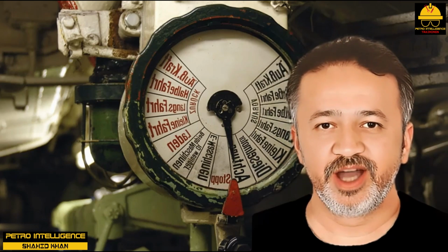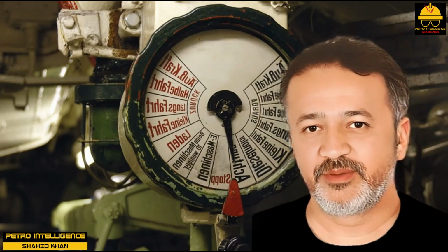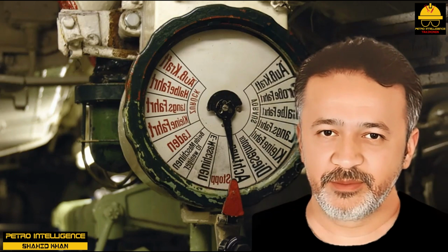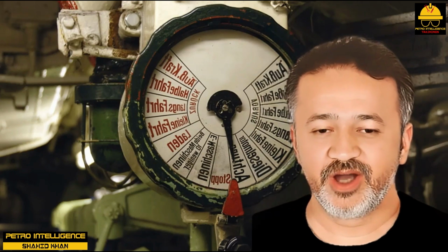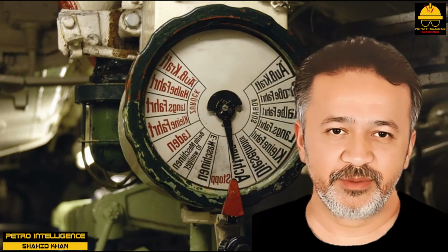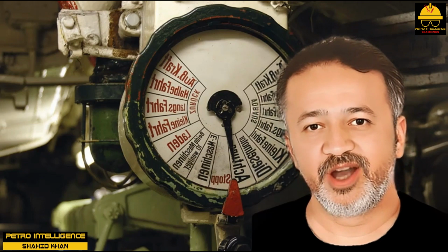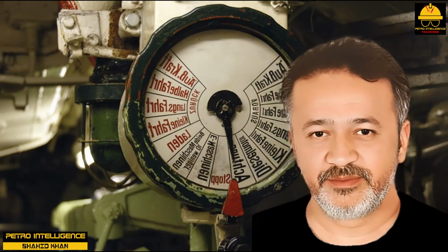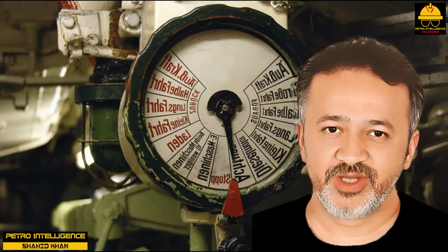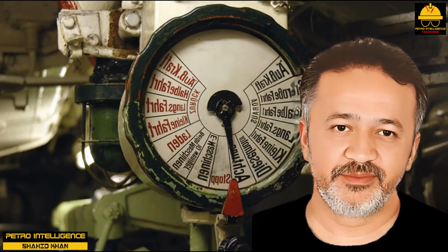The hardwire interlock usually involves electrical relays that operate independently of the control computer. In many cases, they run side by side with the computer softwire interlocks. However, hardwire interlocks cannot be bypassed. They must be satisfied before the process they are part of can take place. A permissive is a special type of interlock that controls a set of conditions that must be satisfied before a piece of equipment can be started.